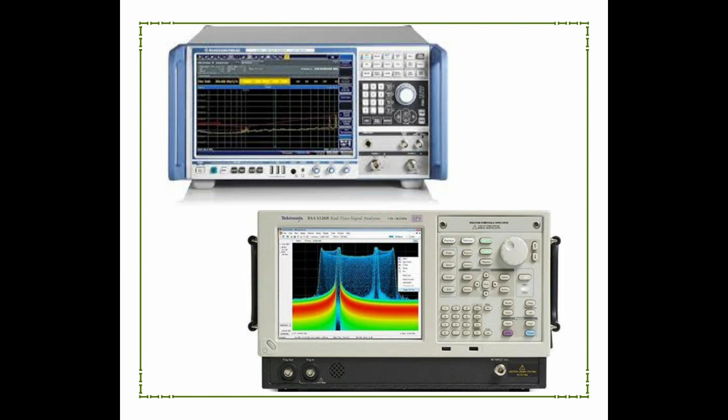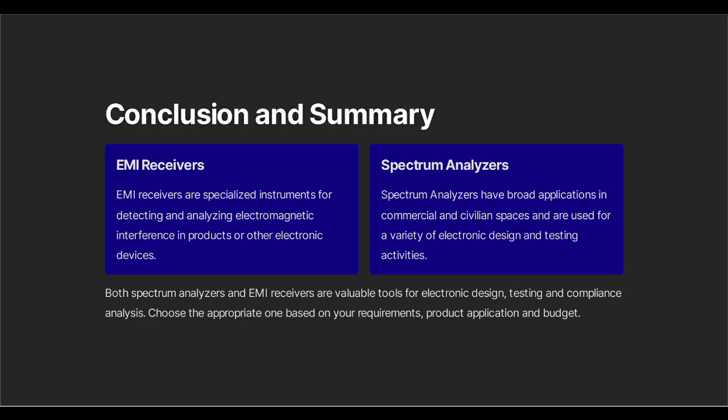Then the CISPR 16-1-1 standard gives the requirements such as detector type, resolution bandwidth, selectivity, harmonic suppression, input impedance, dynamic range, noise threshold and so on of voltage, current and EM field measuring devices in the frequency range of 9 kHz to 80 GHz. Commercial EMI receivers fully comply with the CISPR 16-1-X standard family.